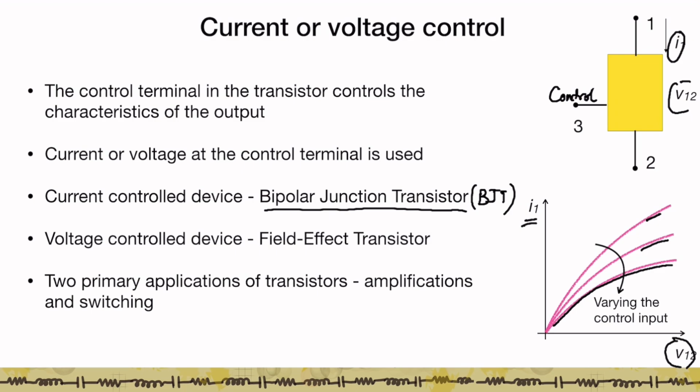Now, broadly speaking, as I mentioned, transistors are used for two applications. One is normally amplification, very simple signal amplification. So what does signal amplification mean? It means that you want to increase the power in an input signal. The other general application is known as switching, where you want to switch the state of the transistor from one stable state to another stable state. Now these two broad applications, sometimes for simplicity, break down into two different kinds of transistor design, if you will, an analog circuit design technique or a digital circuit design technique. But more on that later.